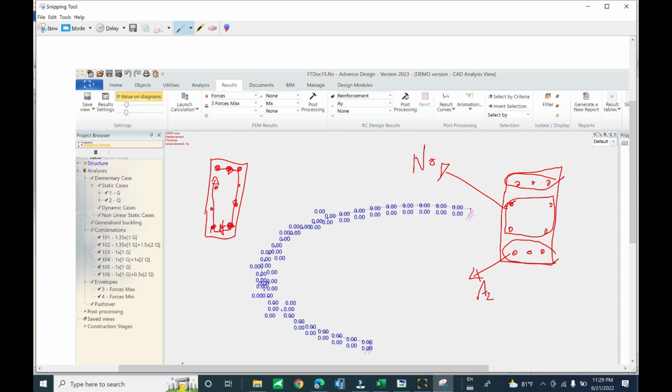Okay, you can arrange the rebar like the section or column. Use the similar concept. This is for the longitudinal rebar, and for the shear we also use the same. For the torsion, we use the outside link as the main link. I call it outside link or outside stirrup. It receives the torsion. You can check the torsion flow in this direction. So the outside link is very important.